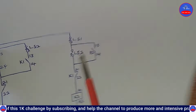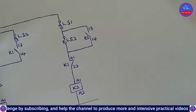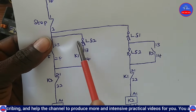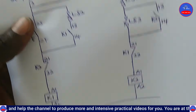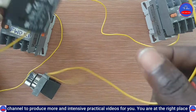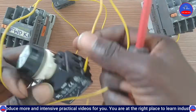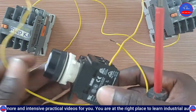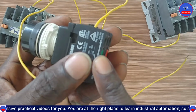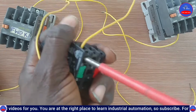All right, and then right now you tap again from the start push button. Okay, you wire this from here to one side of the close contact on the limit switch 2. Okay, so the start push button, the 23, this side. Yeah, so push it here.